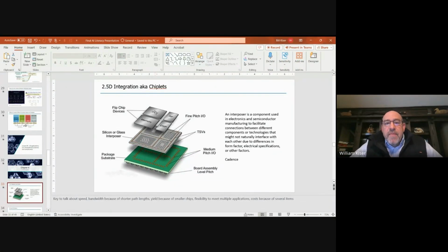You can now also mount different types of chips. Now you, of course, could do that on a circuit board, but you had latency, right? So now you can start to mount your basic CPU, your memory, your DSP, your FPGAs. You can now start to mount these all in what's called a silicon interposer. It's glass. It's made specifically for the application. And then you're able to take the glass interposer. It helps with heat mitigation. It helps with integration in general.